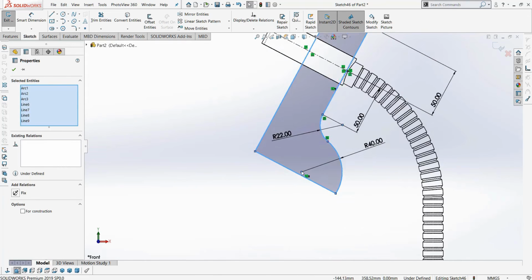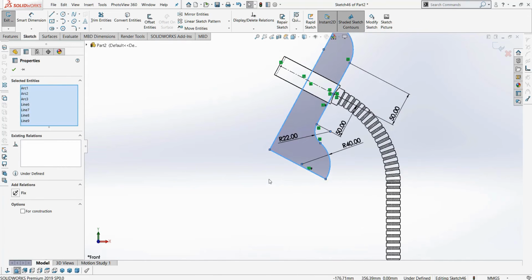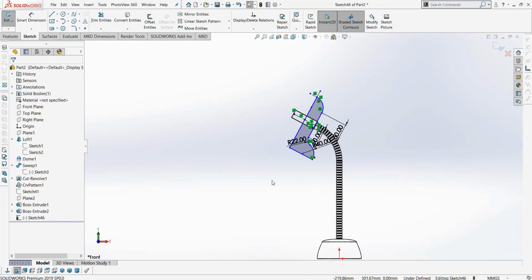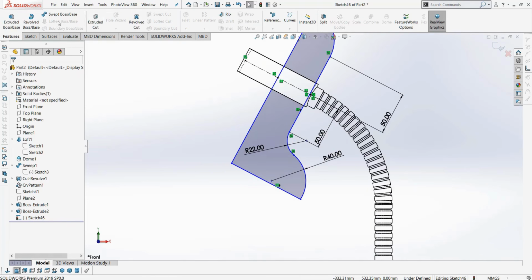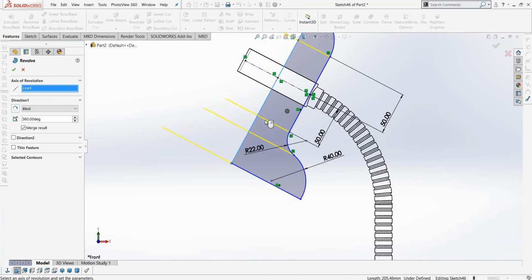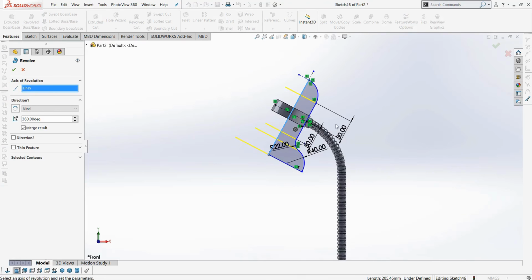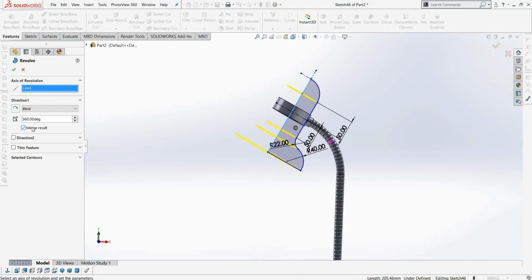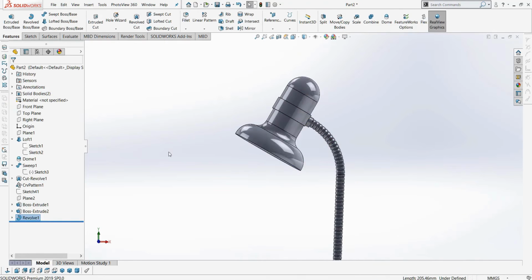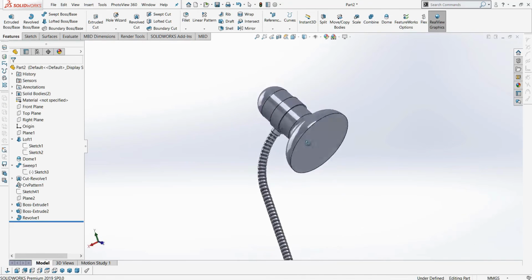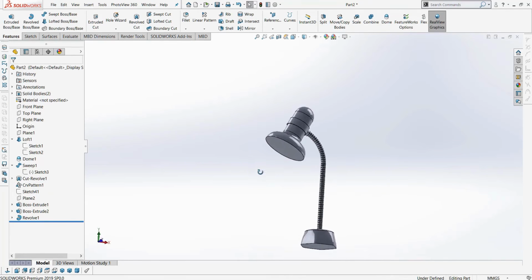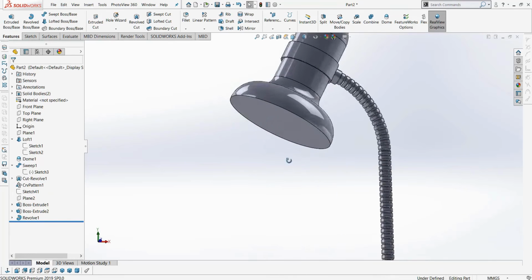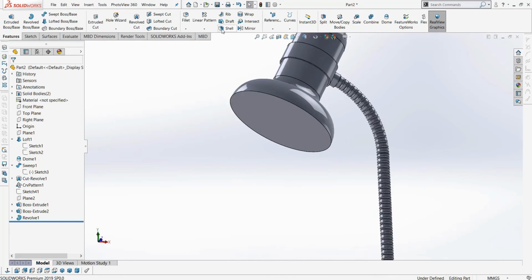Well, you see, the highlighted area means that our entire sketch is closed and ready for rotation. Now the design is just for reference. I'm going to hit the revolve button. Yes. Now the merge option will also turn off. It wouldn't have made a difference if it was on. You set the distance, and it prepared such a form for us. So far it's okay.